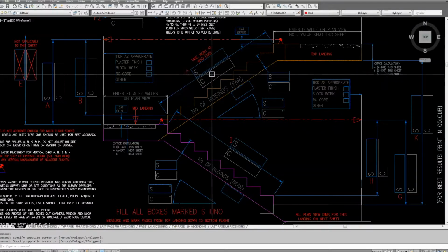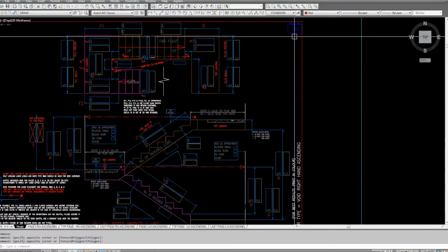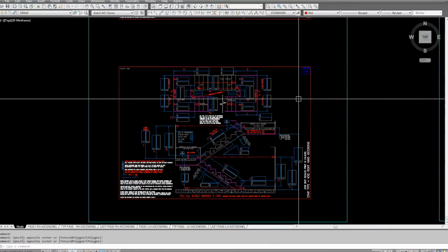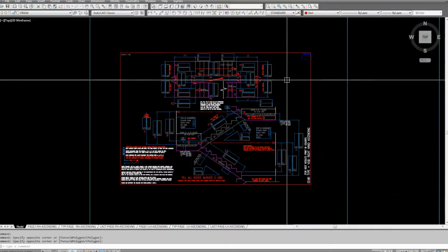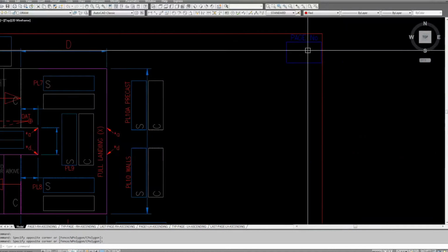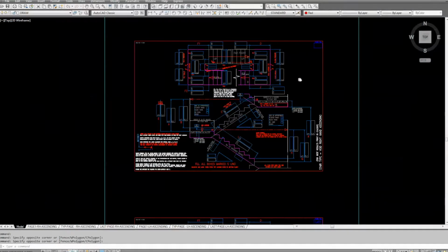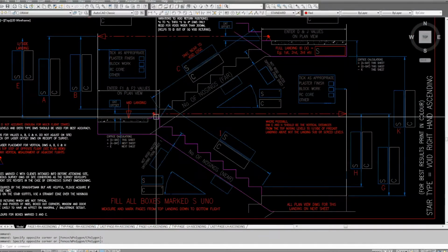Before I go to site, I'll print these off. So I'll print one of those. That's the bottom 2 flights, and then if I've got 8 flights in between, then I'll print 4 of these and fill that in. So looking at a typical mid pair of flights, I put a laser line on.